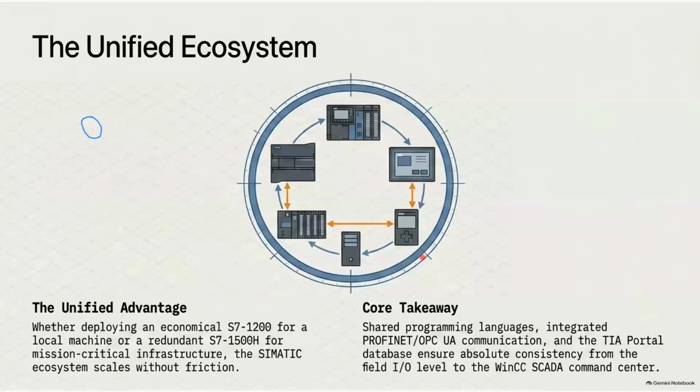If the communication protocols are different, we still have communication hardware that converts the data from Modbus to Profibus or Profibus to Profinet. Those options are available now. So now we can integrate any sort of machine or PLC into our SCADA system, and we can make a single ecosystem.